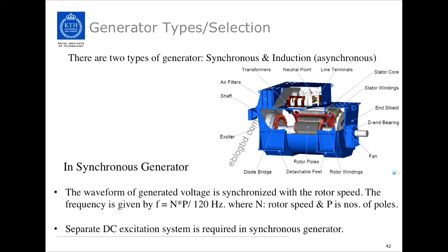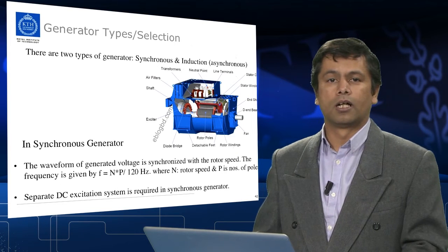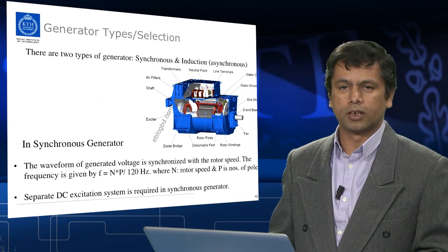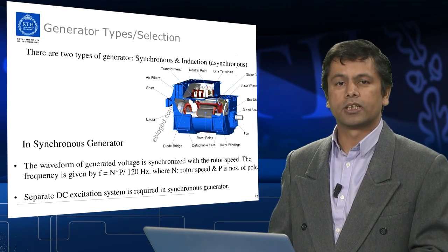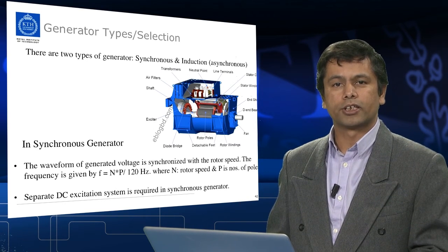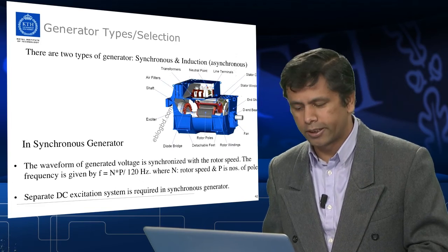But if you want to connect the power plant to the grid with a little bit larger size of plant, let's say a 1 megawatt or 5 megawatt plant, in that case you can use even the induction generator, and induction generators are manufactured in that range, so you can get one directly. Whereas in the small range, the induction generator itself might not be available, but you have to make an induction motor run as an induction generator.